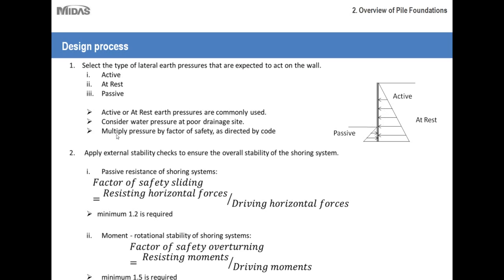And then you need to multiply by the factor of safety as directed by codes, depending on where you're working. The safety codes might vary, so there might be different factors of safety. So it's really important to have an understanding of the codes that are being used in your area as they apply to short excavations in the design of these walls.